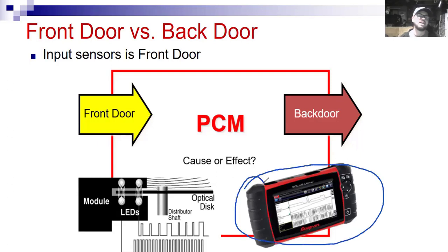It's processed. And there are times where the scanner could possibly lie to us or mislead us, especially if we're in the manufacturer side of the tool. But still, that scanner is very, very powerful, and we just have to keep that in mind. So I'm always a little suspect, and really it's always better to measure sensors directly.